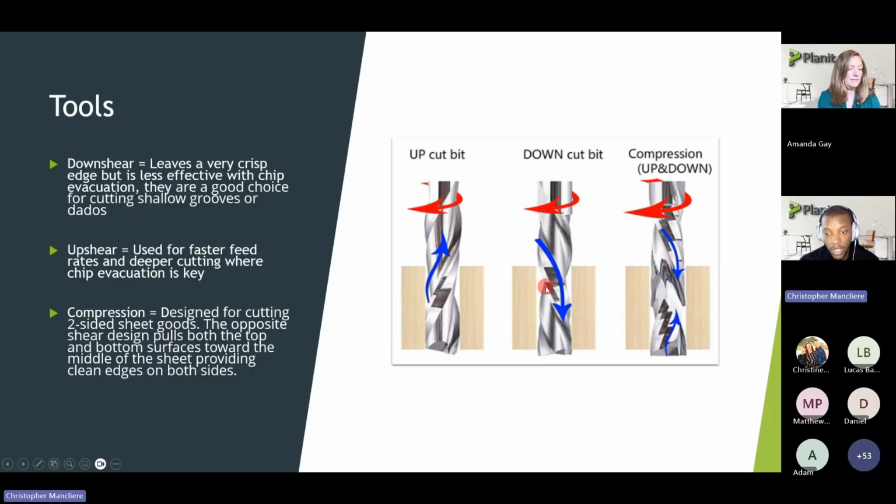If you do, like, a 1/4 inch or 1/2 inch dado that's not going through, because you don't go very deep, this will guarantee that your dado doesn't have any chips at the top, but also the dado is not deep enough to get the chips stuck at the bottom. If you're going in one shot, for example 3/4, as you move you will see more and more buildup around the tool, and that could damage or break the tool, or make the part move because the chips will try to expand around the bit. So that's the down cut bit.